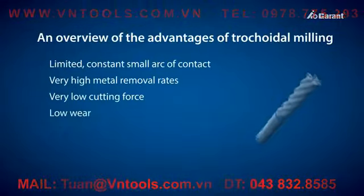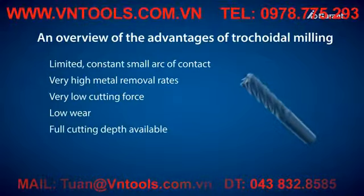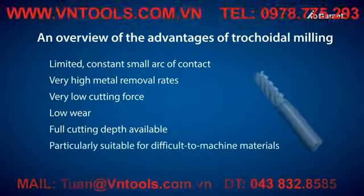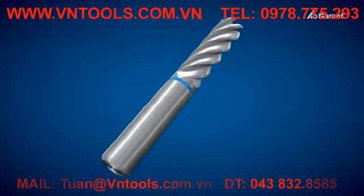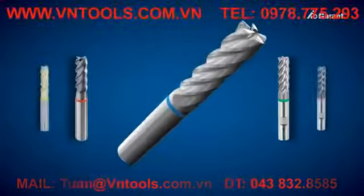Machining can be at the full cutting depth from the start, whilst achieving low wear. Trochoidal milling is particularly well suited to difficult-to-machine materials. The greatest benefits are achieved for hard machining and for machining stainless and superalloy materials.